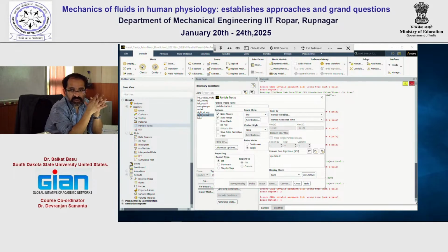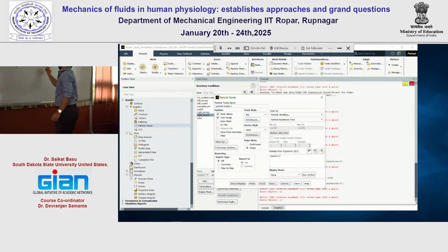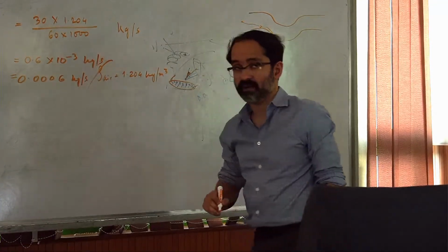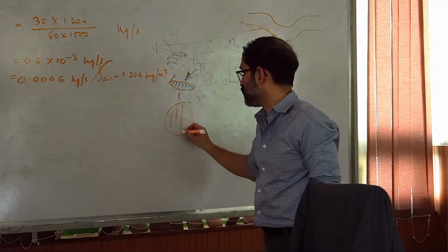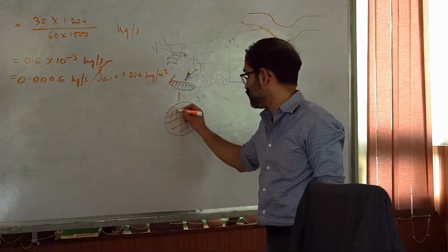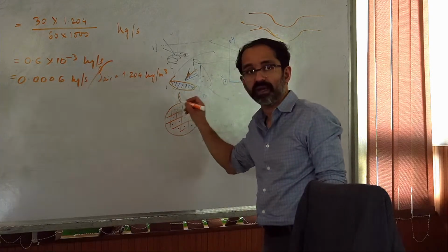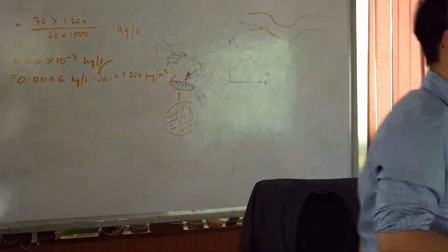So when we set up the surface injection, there is no option to set up streams, right? What ANSYS does is, once you have the surface injection, it looks at the surface that I have defined that the particles are embedded, and looks at the corresponding mesh. I'm drawing it very simplistically, whatever the mesh is on the surface. It picks the centroids and embeds the particle at those points. So how many particles would be tracked hence becomes a function of the mesh.